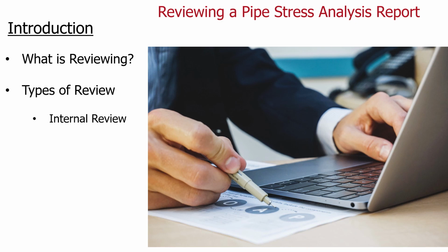One is called internal review. What is done in this case? Each stress analysis report must be reviewed by a senior engineer before issuing it to the client. For example, if my company is performing the stress analysis and it is done by some engineer, then the report must be reviewed by some other senior or principal engineer, who is more experienced than the person performing the analysis. This is called the internal review.